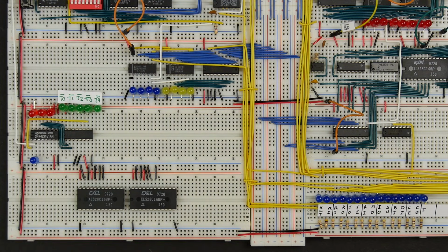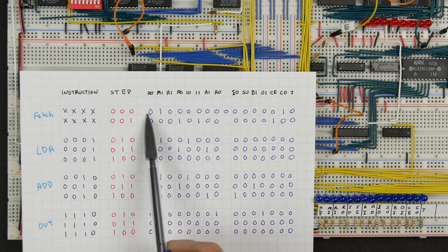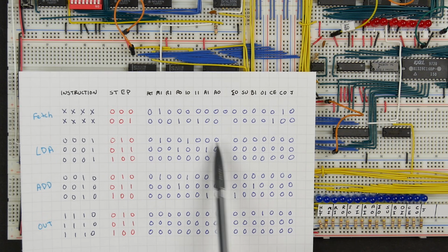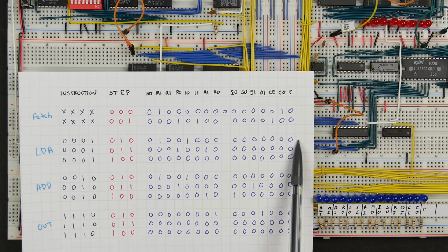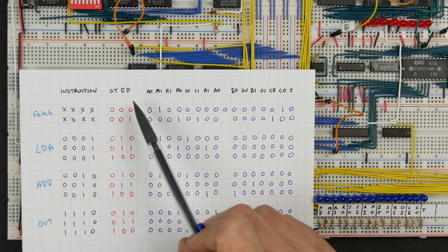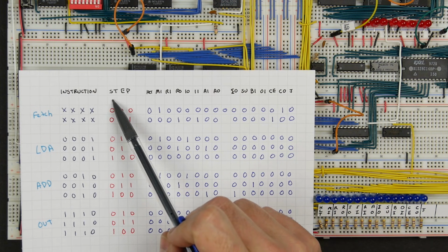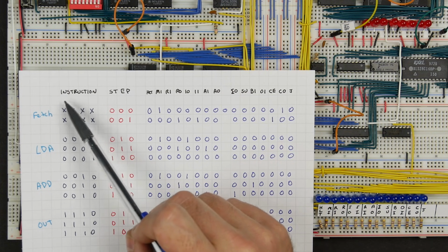And those are the signals that we want to use, right? So we have 7 address lines for our inputs, and then for each chip we've got 8 outputs. And actually here we're not using one of those, but that's okay. We might find a use for it later on. So what I'm going to do is set up these as our address. So this will be A0, A1, A2, A3, A4, A5, and A6.